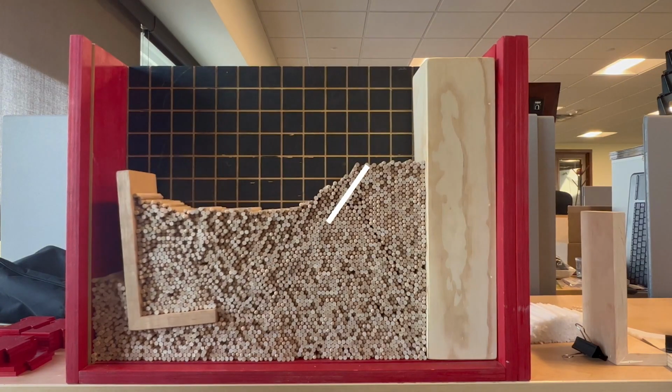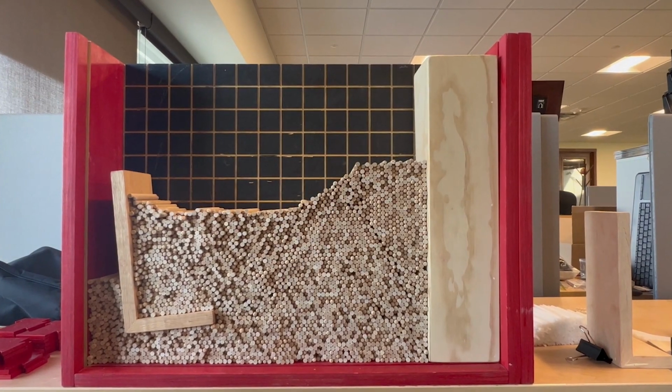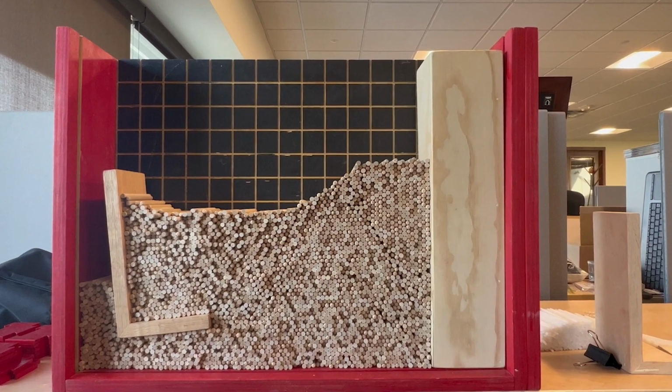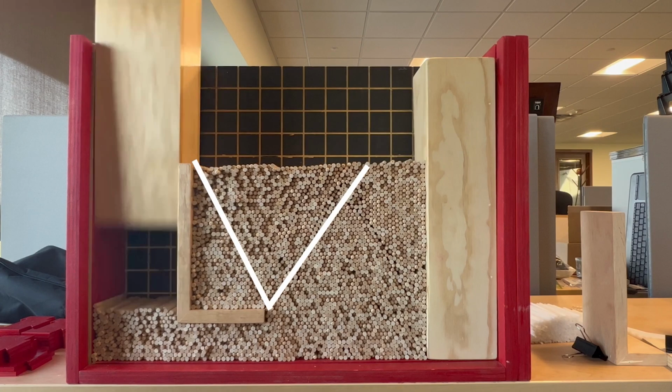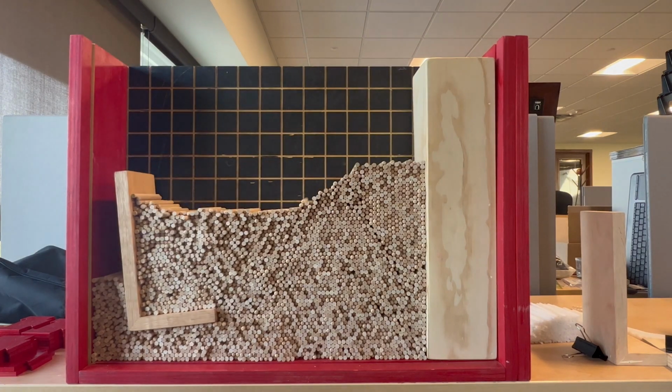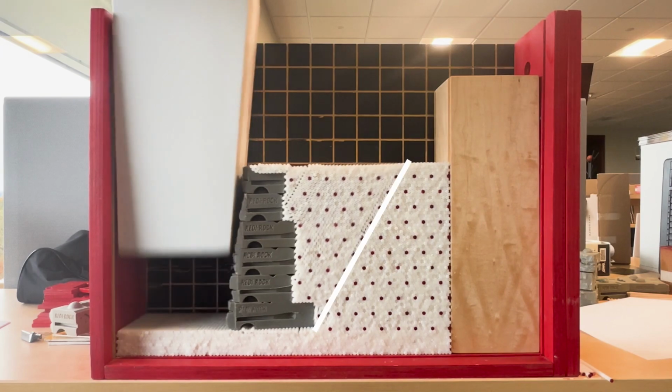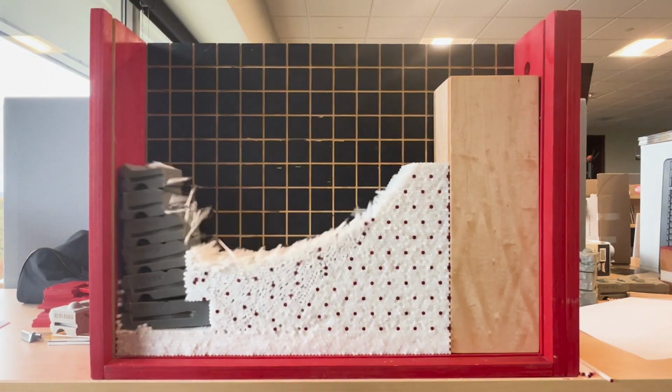When we move the support out of the way and things start to move, just as expected, you're going to see this failure plane that forms from the back of the heel on the wall. It's also interesting to note the failure wedge that develops above the heel. Part of the supported soil actually acts like part of the wall to resist sliding and overturning. The last wall we'll look at is a PMB wall with 3 different width units. Again, the failure plane forms at the back bottom corner of the bottom unit.